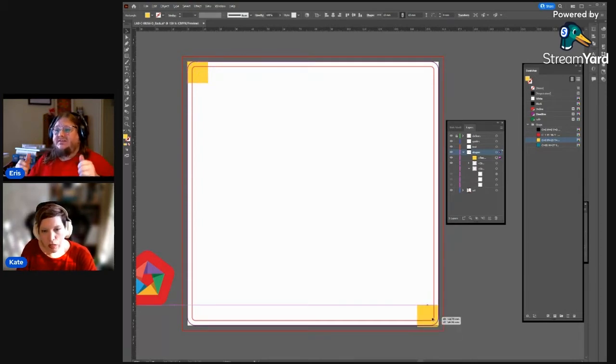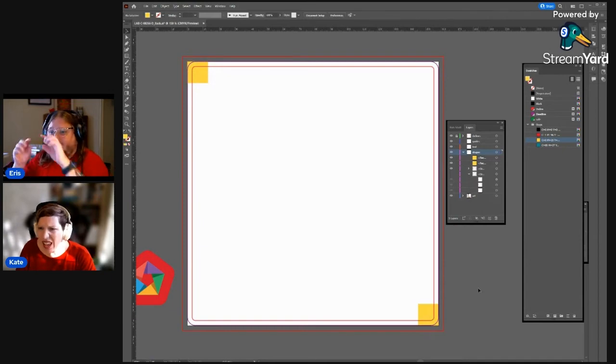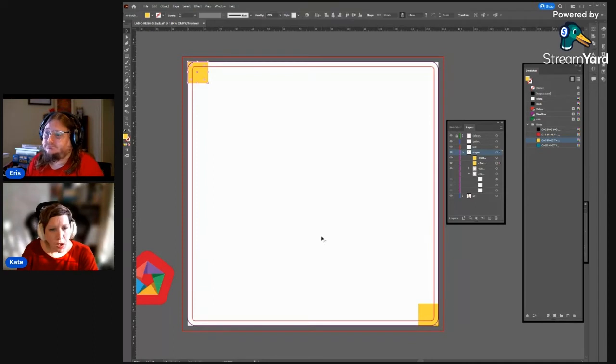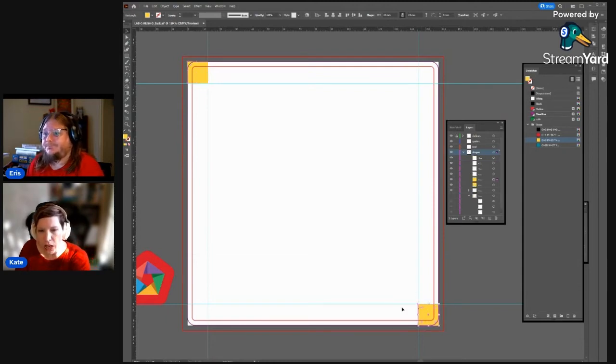I'm going to go with 10, because 10 gives us that rigidity so that it stops it from being horribly floppy. So with those little squares, the next thing that I'm going to do is set up a pair of guides that basically mark out the edge for that corner and that corner. These don't have to be perfect. It just has to be reasonably close. Then I'm going to get rid of my squares because I don't need them anymore. So what I'm looking at here is I've got 4 guides.